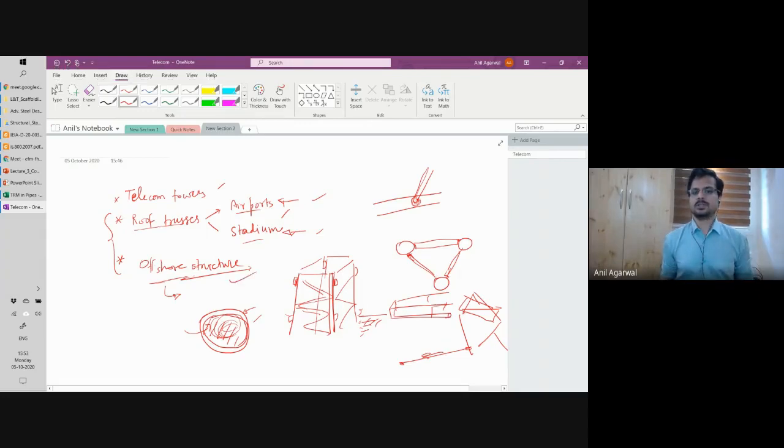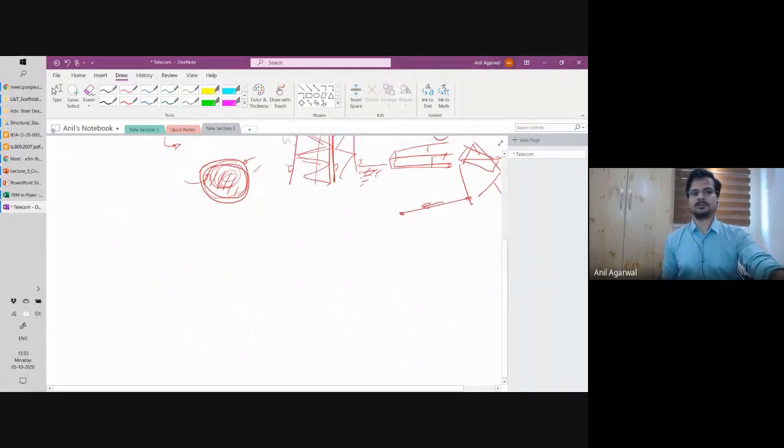So that is a special application where they use, and there, having a hollow section helps. And there too, welding is the primary mode of connections. So connection issues are handled here this way. In telecom towers, the connections are of slightly different kind. In telecom towers, you have tubular columns, or main legs are tubular. Again, I would recommend, when you come back to the campus, look at the Reliance Tower near the canteen area outside the campus, but it is right at the corner.